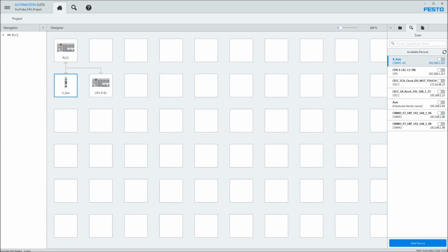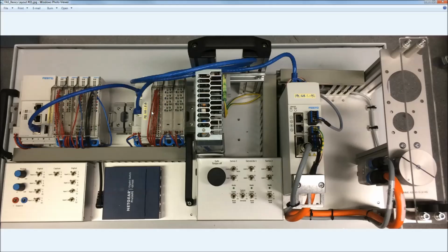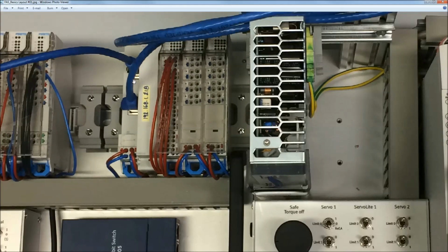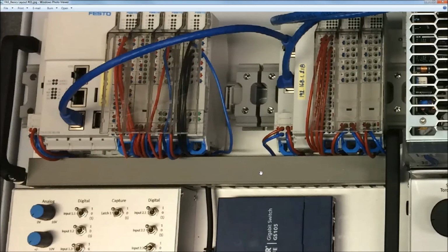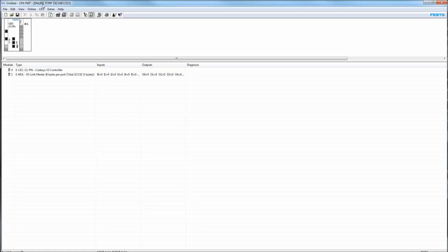That's because if you look at the layout here, I have two ports here. Both of them are EtherCAT. And the way EtherCAT works is it's closing these ports and you can't get in. You have an option to activate EtherCAT or Ethernet over EtherCAT, EOE, but the PLC, in order to talk to this with the scan software that's embedded in the Festo maintenance tool, as well as the